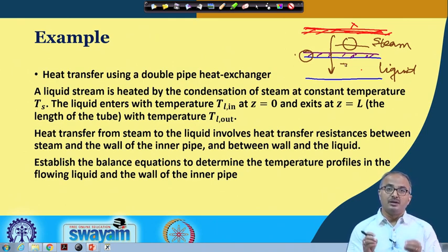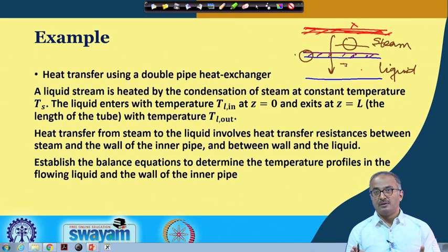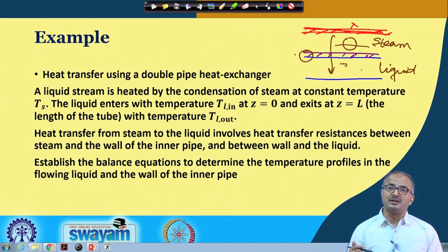You can easily figure out that this radiative heat transfer will be effective only when the delta T is quite large. So we are also neglecting the contribution of radiative heat transfer for the kind of applications we are talking about. But this is not a mandatory assumption. You have to first check the difference between the temperatures of the hotter and the colder fluid.